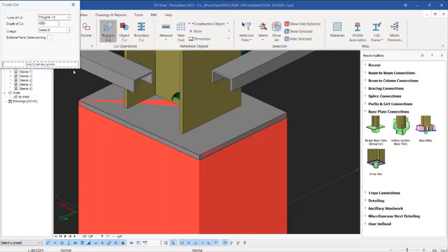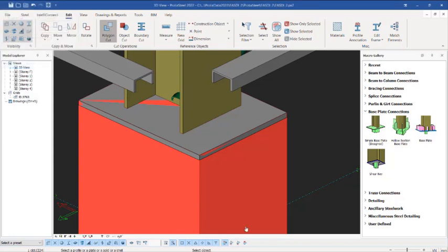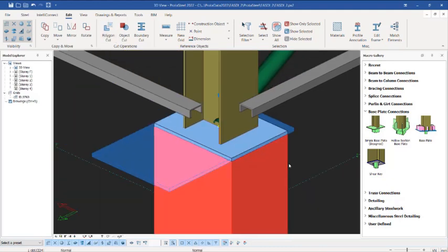So click on the polygon cut, so you can see the depth of cut is 1000. We change it to 500 just like this. So we click on select part and then point. The part we are going to consider is the reinforced concrete column, so you select that. So for the area to be cut, pick this first point. You just follow the way I'm doing. This point, this one, and this one. You see it has cut that part off.